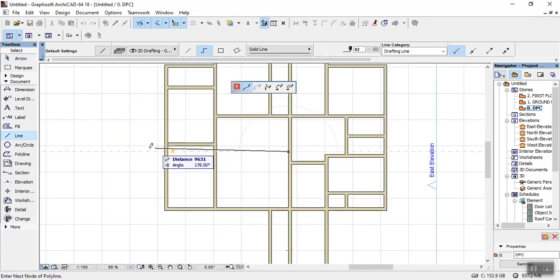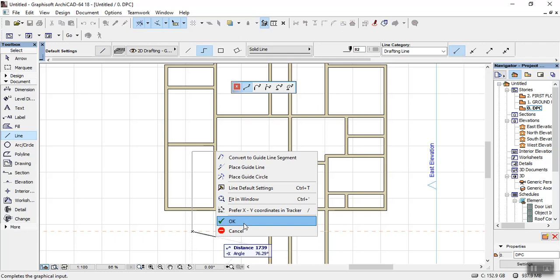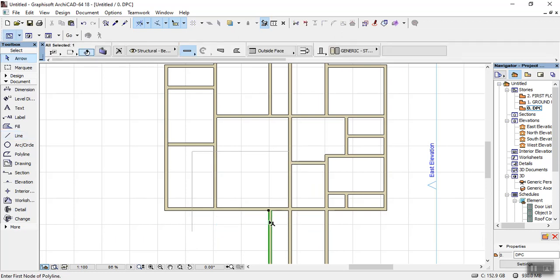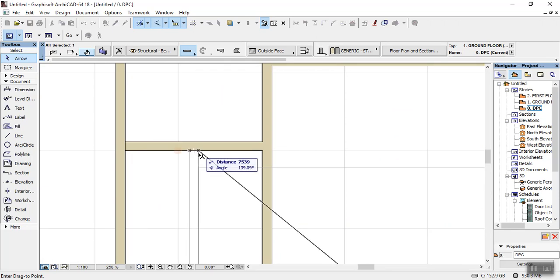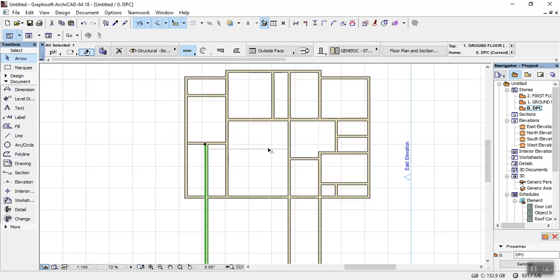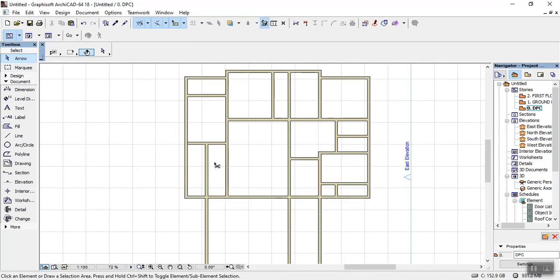From this wall to this wall, that's 6900. Okay, that's the final wall there. So I'll bring this wall down to this spot. I'll copy. You can take a wall from anywhere to get what you want. Okay, so I'll delete this wall, then I'll take this wall off and take this wall off.